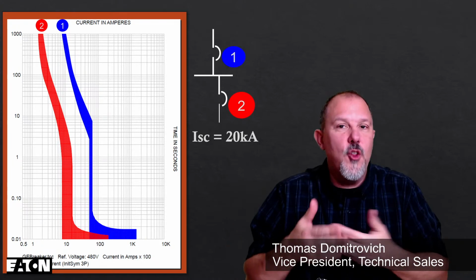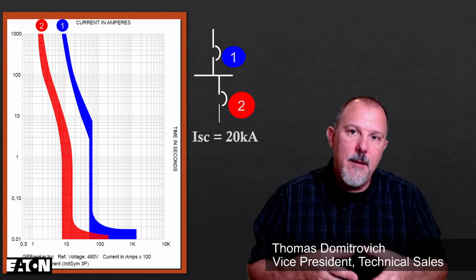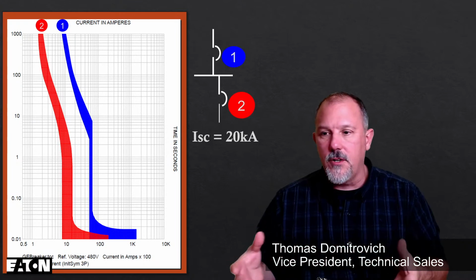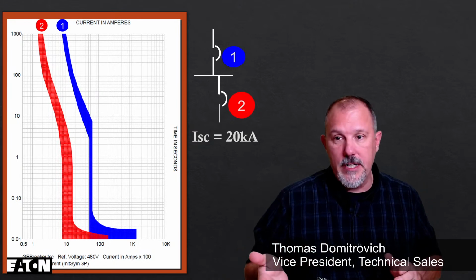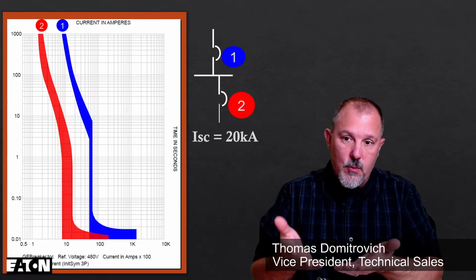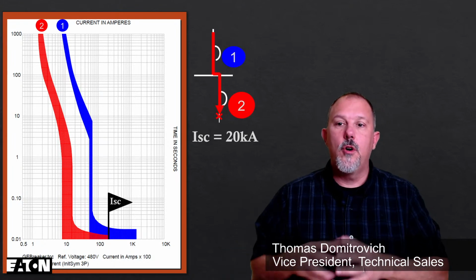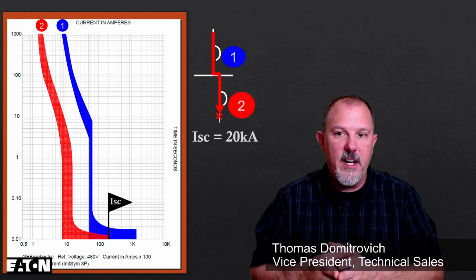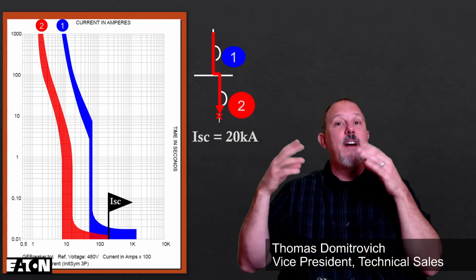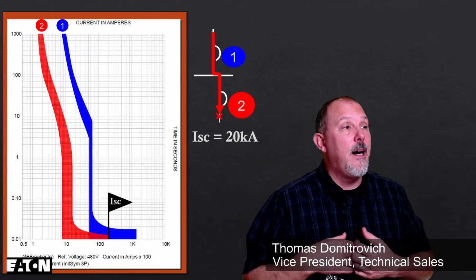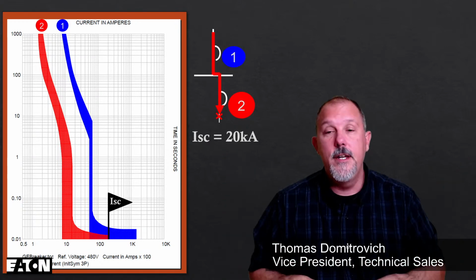That's where the blue and the red curve overlap with each other. And typically, SKM, EDSA, Easy Power, and all those other applications will cut those curves off at the available fault current. If this was cut off at the available fault current, then your bolted fault current value would be about right there, which would mean it's in the instantaneous region of the upstream device, which, if I was selectively coordinating, would be what my good friend Tim Cernko terms as being ungood.